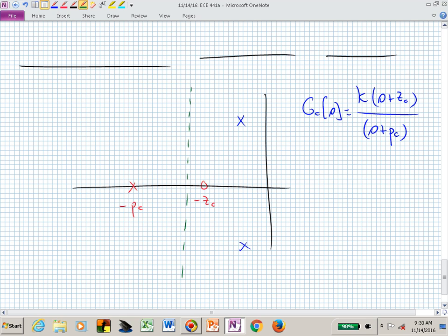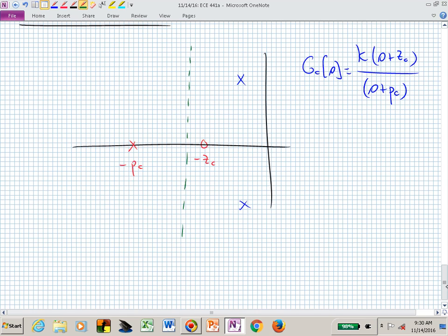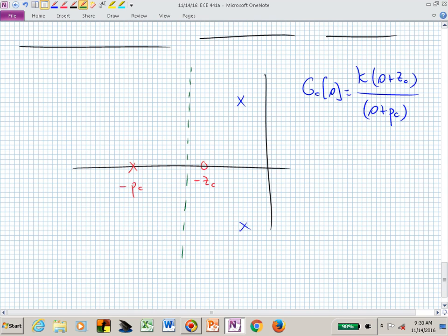And now, what's going to happen? Well, you could have all sorts of pictures depending on the separation of the pole and the zero. But probably what's going to happen is these will go this way towards the asymptote, and this one will come in here. Right? So you're trying to locate that asymptote far enough to the left to achieve your settling time specification.